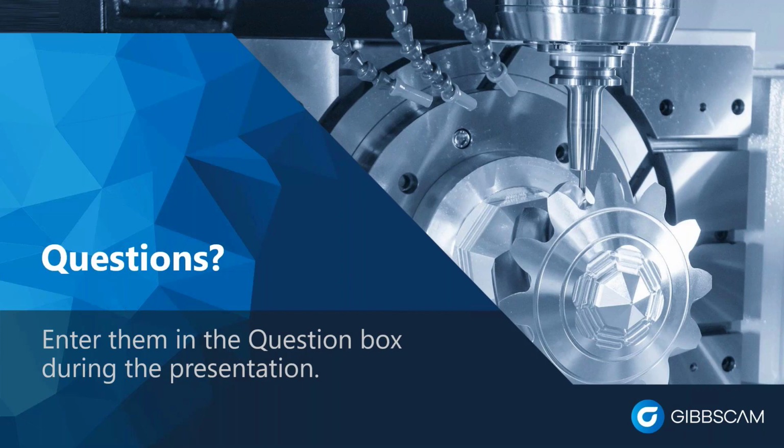Does the GibbsCAM 5-axis support TCP and dynamic work fixture offsets, or DWFOs? Absolutely, yeah. The TCP is for 5-axis simultaneous, and as long as your machine supports it, the post and GibbsCAM will as well. And the DWFO, dynamic work fixture, that is for 3+2 machining typically, and yes, absolutely, all our posts support that in 5-axis.